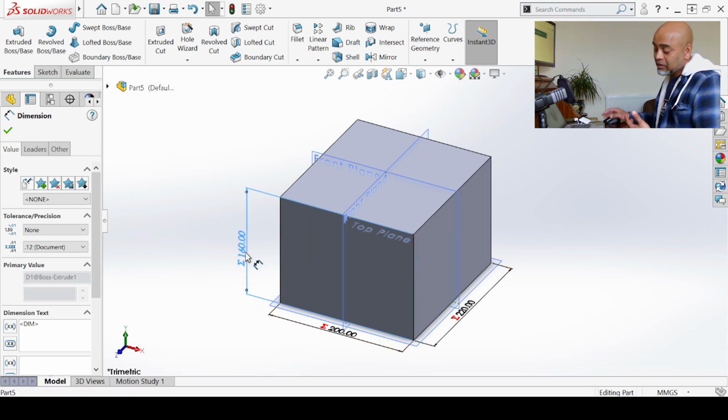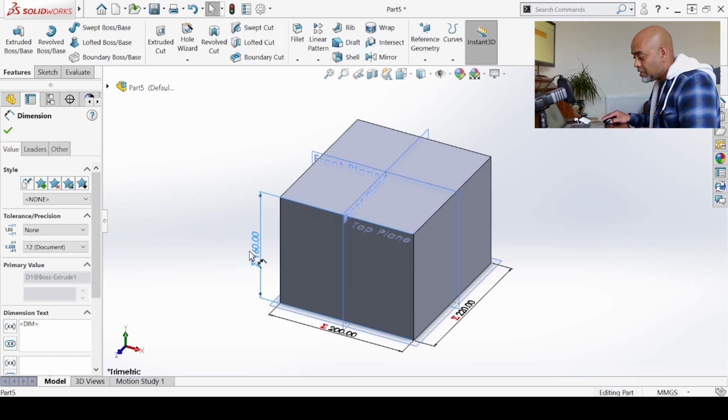Okay, so this is what I call creating variables, linking them up. There's also a way of getting Microsoft Excel to talk to SolidWorks. So you could be running some complicated maths, and some equations could be dictating a variable you need to bring in. And you want that to be a dynamic relationship every time you run the Microsoft Excel or MATLAB, probably for that regard, because you can connect MATLAB to Excel and now Excel to SolidWorks. And you could actively read the cell value to be able to change your object and be organic.